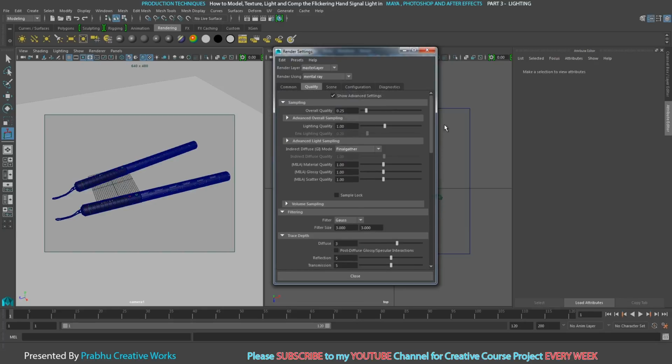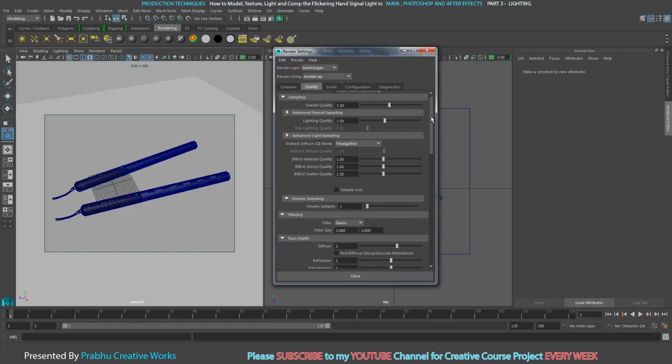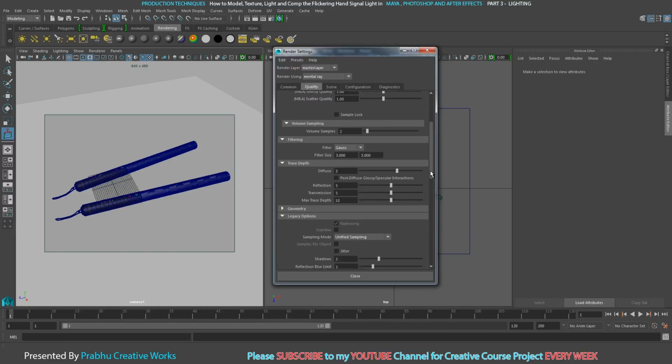So it will be available in here. Volume sampling, you want to give at least 2 samples. So here we have overall quality set to 1. So sampling we have that, and give volume samples to 2, at least 2. Okay,